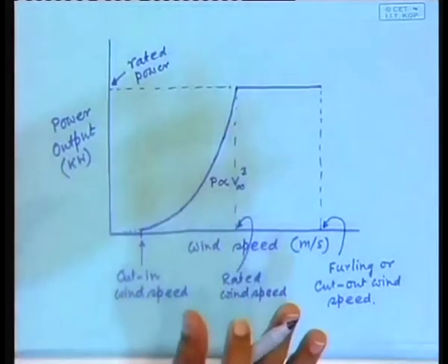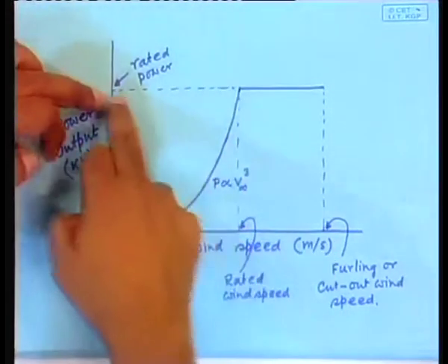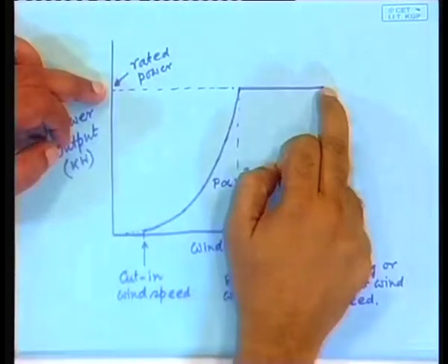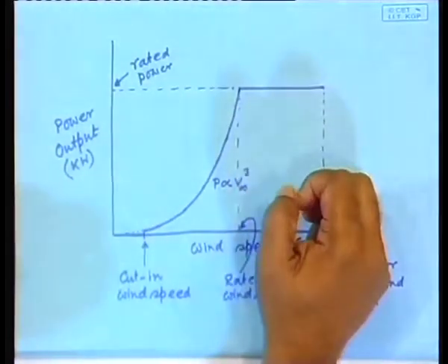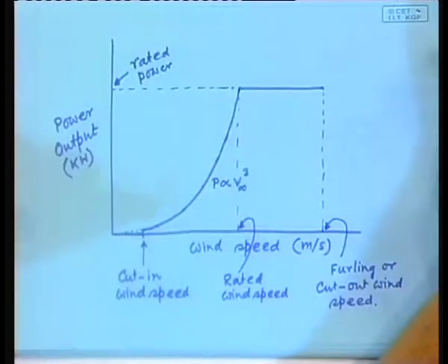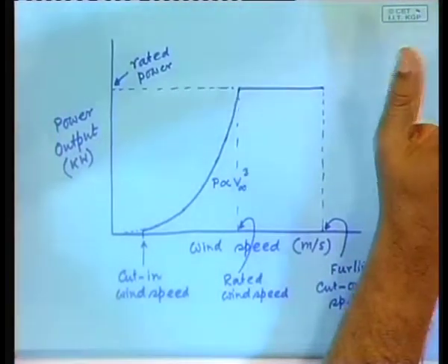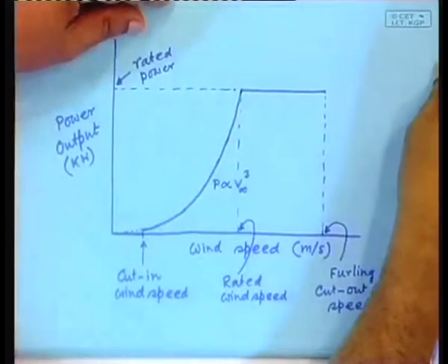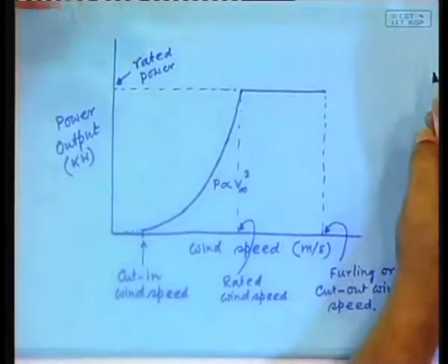This is the standard wind turbine characteristics. Only let me also mention that here we have argued that you should not go beyond the rated power output, which is a logical argument. You should not go beyond the rated power output, but there exist certain generator configurations which can allow one to extract say 30 to 40% more power output without overheating. What these are, I will come to that later. But there exist this kind of electrical conversion mechanisms by which you can do that.